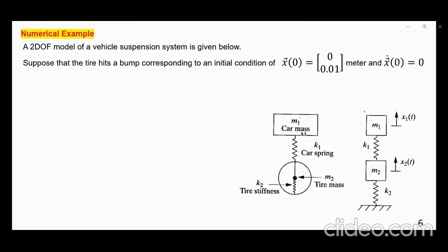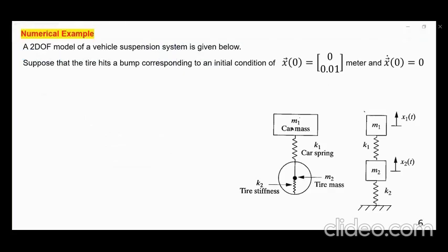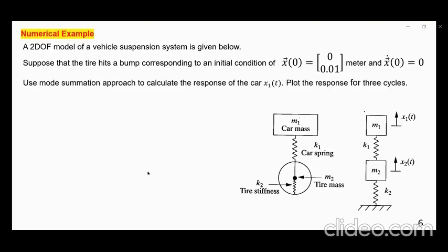This M1 is called the sprung mass, and this M2 is called the unsprung mass. So we can represent this thing physically or graphically like that, but effectively it represents the mass of the car and the mass of the tire or tires. The same thing with these stiffnesses. This represents the stiffness of the tire, and this represents the stiffness that's coming from the suspension of the car. Now, we're ignoring damping here.